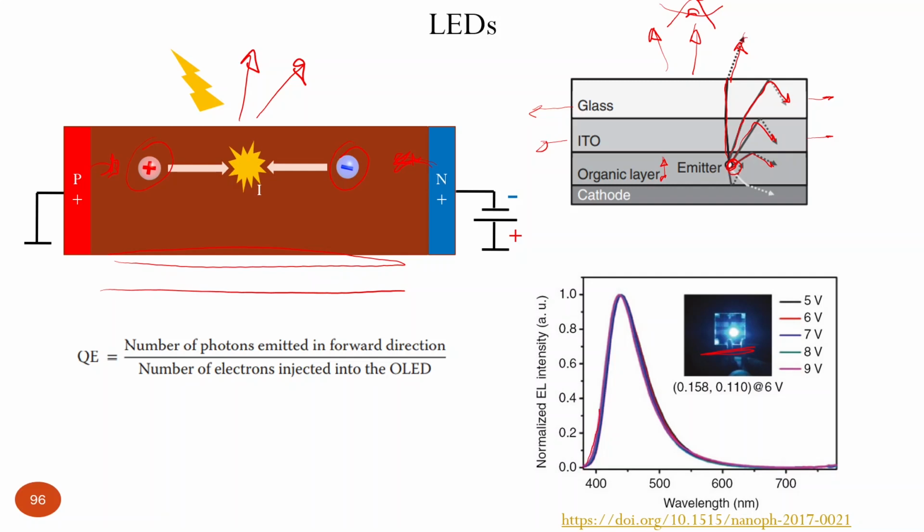And that will be a spectral distribution with a maximum corresponding to the band gap of this material. So it's not a monochromatic light source, it's not a laser, but it's a relatively narrow spectral distribution because it is peaked at the position of the band gap. If you want to change the spectral distribution, you use a different material with a different band gap, and you could see something like this. You could see these peaks at different wavelengths, which correspond to different materials. Of course you can combine them together, so you will get some spectral distribution.